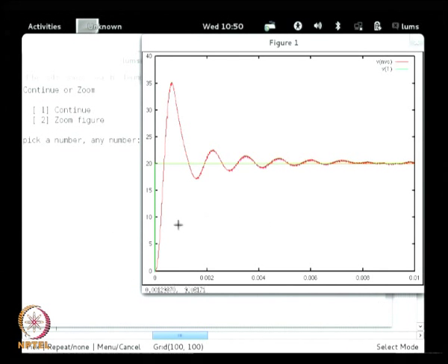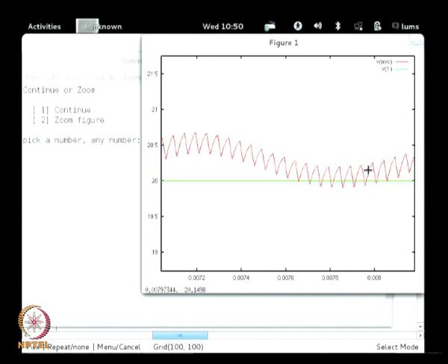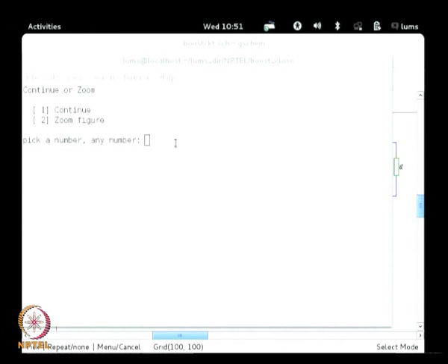So, you see that the green waveform is node 1, which is actually the reference, and the output voltage is trying to get controlled and reach a stable state. You could zoom in and try to see the nature of the ripple, calculate and study all those characteristics.